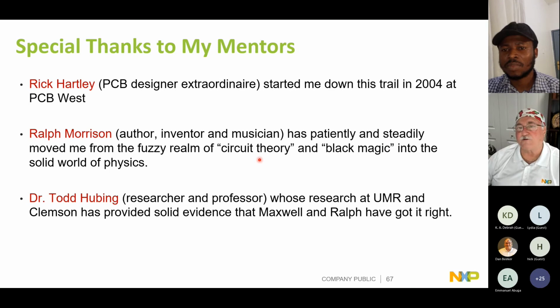I designed my first network control board a couple of years ago, a gigahertz 28 nanometer network processor running with 400 megahertz DDR4. I had an Ethernet control processor. There were Ethernet switches. This board had SerDes and PCIe and Ethernet and CAN and LIN and everything you could imagine in Aurora interfaces. 60 picoseconds was everywhere. Two PMIC and two switching power supplies. I took 26 inductors and ferrites off of the reference board the company had.